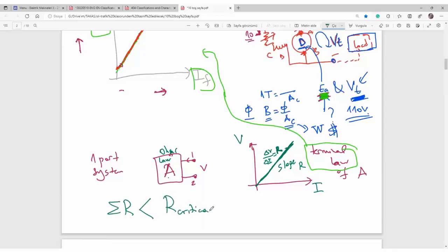Total resistance, you know, is R armature, R startup resistor, adjustable R shunt field, R field controller of the generator, and any added resistances in the loop. The summation of all those resistances must be smaller than the critical resistance, which comes from the no-load curve.